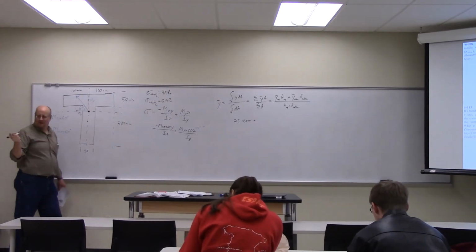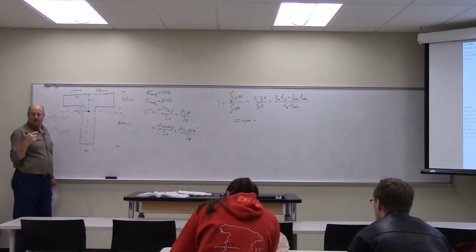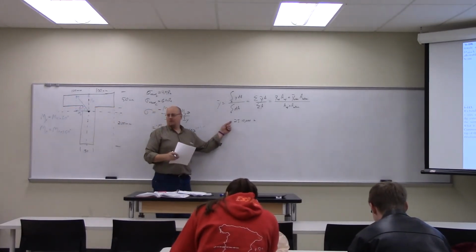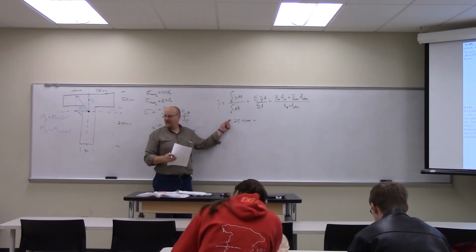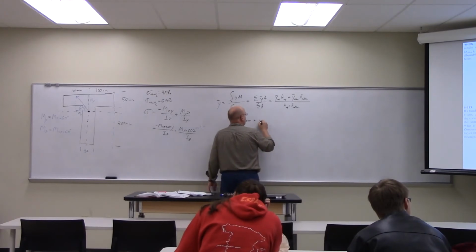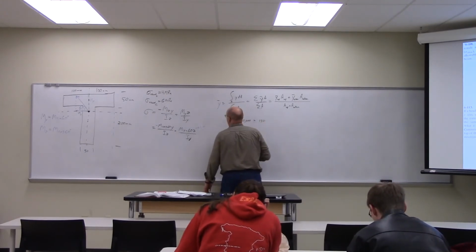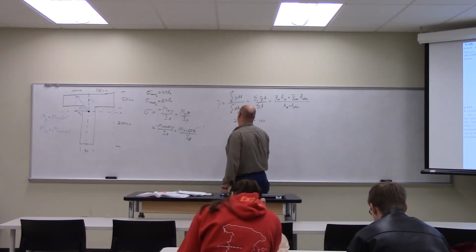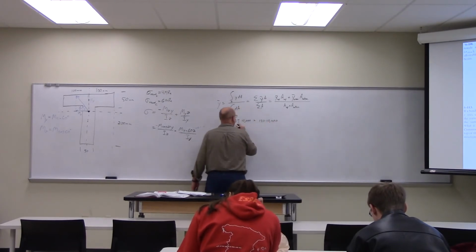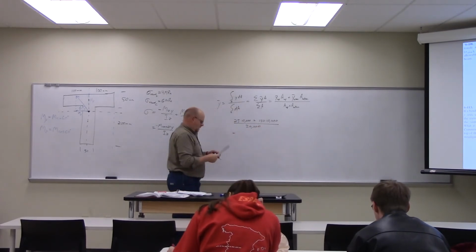You see what we're talking about? Or 100 from the bottom, but you didn't give it 25 if it's from the bottom. Then this one has to become 225. Use the same point of reference for both of them. So 150 times the area of the bottom. What's the area of the bottom? The same 10,000. They're both 2x4s. Divided by 20,000 equals